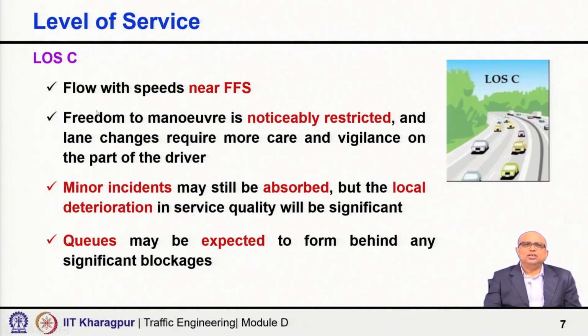Level of service C, flow with speeds near free flow speed again. Freedom to maneuver is noticeably restricted and lane changes require more care and vigilance. It is possible, but more care and vigilance on the part of the driver is necessary. A minor incident may still be absorbed, but local deterioration in service quality will be significant.